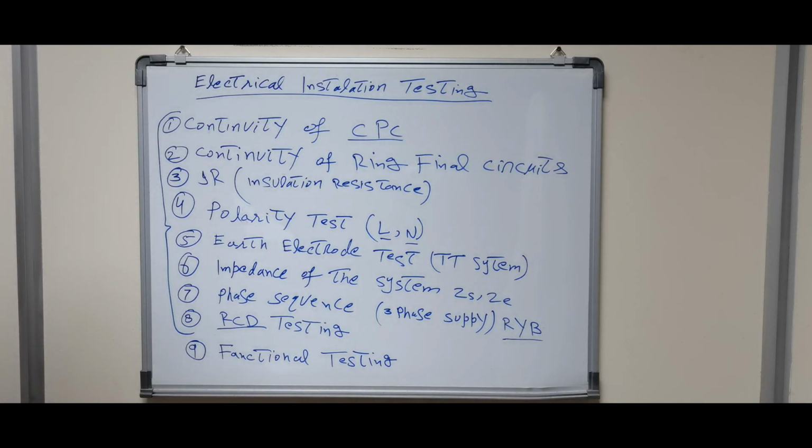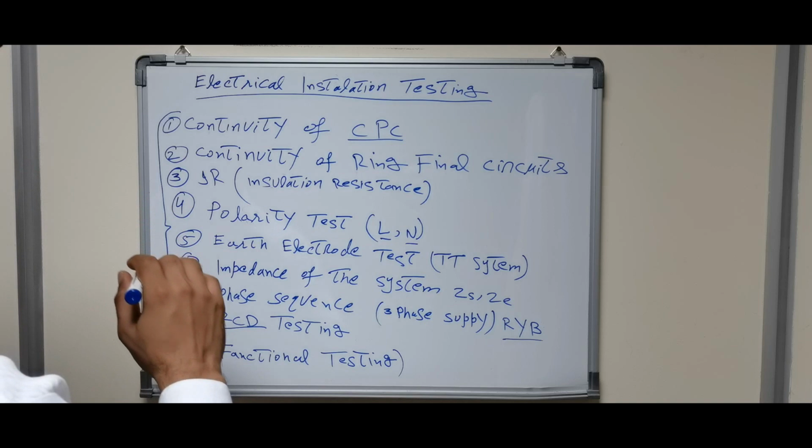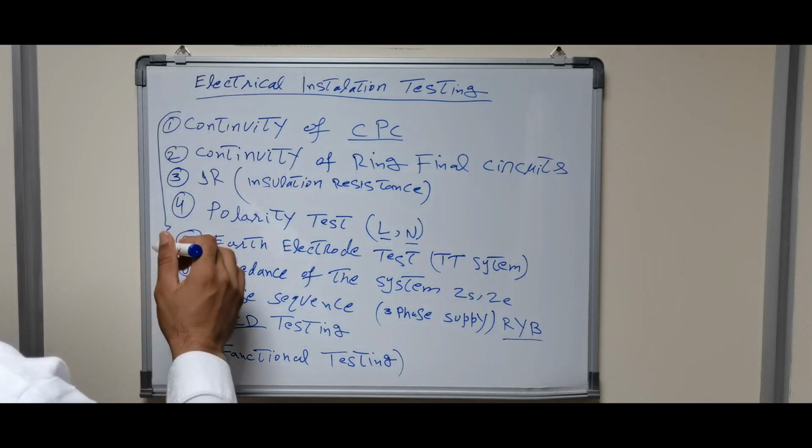At that time we switch our equipments on and off and check the function of our switches, sockets, etc. Although these equipments have already passed manufacturing checks, they can be damaged during the installations. For that, we need to make sure that our switching devices and socket outlets are working correctly.